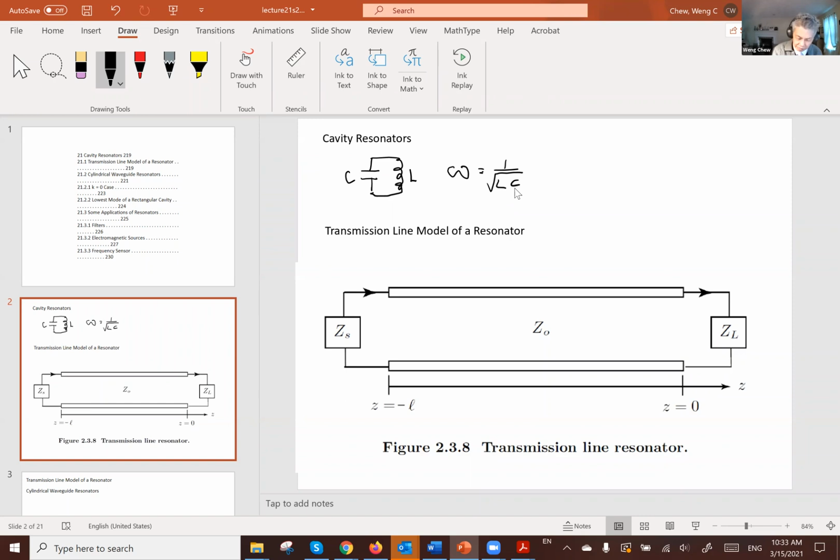For instance, in a circuit, you don't need an external driving source to get the current going back and forth. There will be current going back and forth between the capacitor and the inductor due to the exchange of magnetic energy stored and electric energy stored, but you don't need an external driving source to make that happen. The energy just goes back and forth by itself.